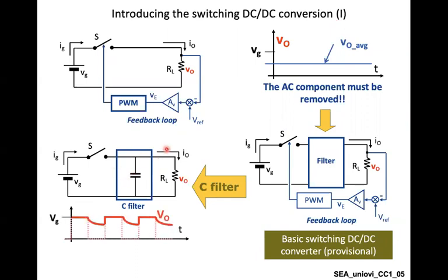Now this will be the output signal. It can be easily understood that whenever this switch is turned on, I mean it's a short circuit, the output equals VG, as you can see, because simply you create a short circuit here. Once this switch is turned off, you disconnect the input, and the capacitor will start to discharge in the resistance in this manner.